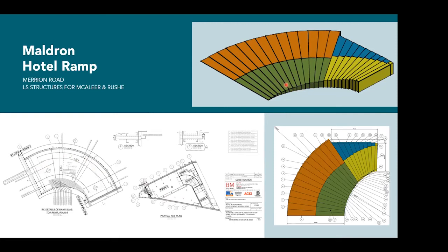We broke it all down into obviously blocks and EPS blocks. And you can see here the level of detail we can go into and what we would supply to the customer as well. So we take it obviously from near enough a 0 point up to, I can't remember what the exact end height was at the end of it. But we're climbing, taking the radius into account, working within the structure that's there, allowing them to form that ramp, because it's EPS lightweight material. The structural engineer works out the compressive strength based on the EPS that's been chosen for the product, works fine for their loadings, and off they go.